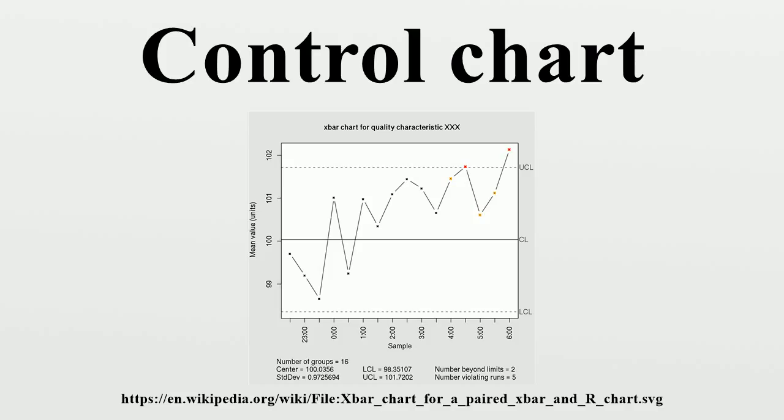The control limits provide information about the process behavior and have no intrinsic relationship to any specification targets or engineering tolerance. In practice, the process mean may not coincide with the specified value of the quality characteristic, because the process design simply cannot deliver the process characteristic at the desired level.